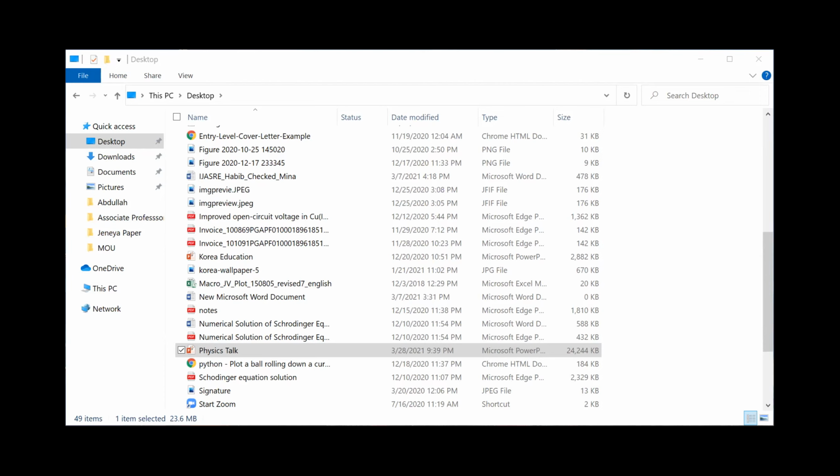Actually, I designed my talk on chalcopyrite based thin film solar cells, and there are several parts of solar cell fabrication. One part I will cover is the efficiency improvement by the solution based, non-vacuum chemical spray pyrolysis method. This is a very easy and cost effective method around the world, and in our lab we use this method for fabrication of solar cells.